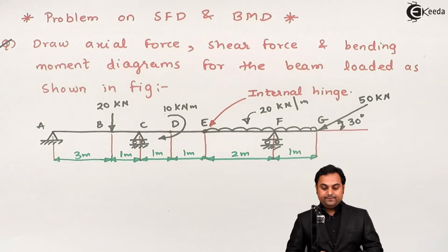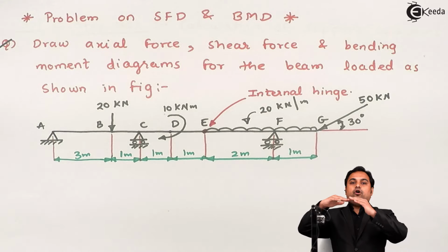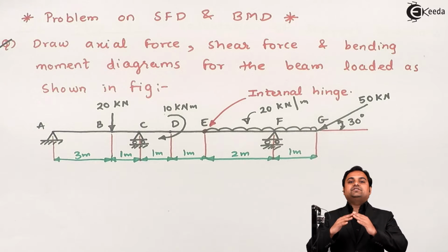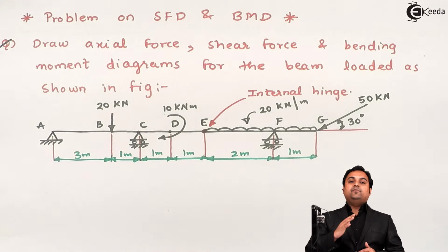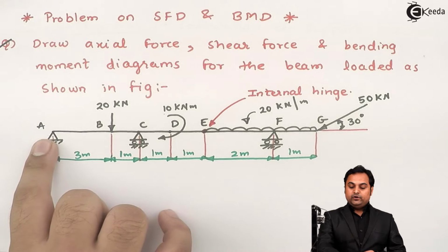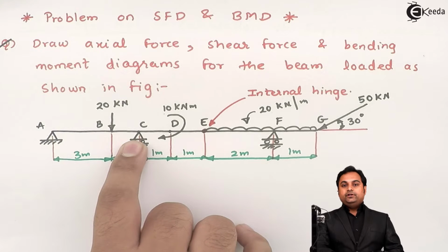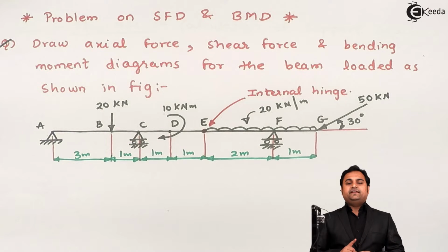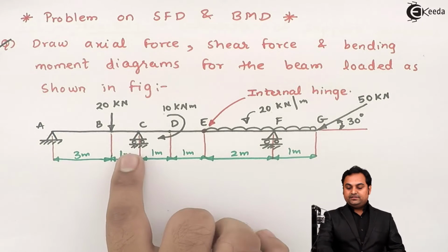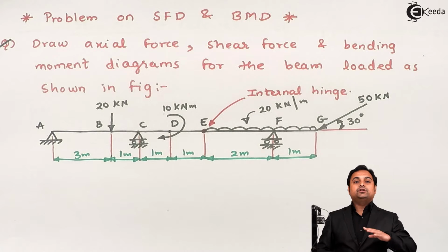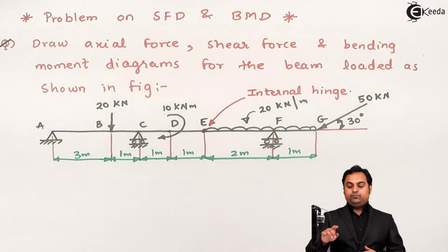Then at the same time, here there is hinge support. Hinge support will offer motion in angular direction. That is, the beam will not move in horizontal or vertical direction, but it will be moving in angular direction. So there will be horizontal and vertical reaction at point A. Then if there is roller support, there will only be vertical reaction, because at the roller when the load acts, the beam can move in horizontal direction and this roller support also offers some angular motion. So there will be only vertical reaction, that is, the beam cannot move down at point C.